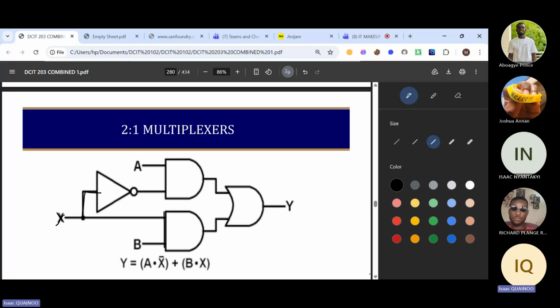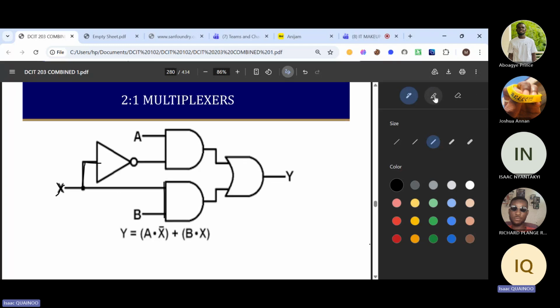We are going to use the same method for other types of multiplexers like 4:1, etc. Okay, so 4:1, we stated yesterday that it has two select lines, right? So S0 and then S1, right? And then the corresponding D output. So if your S0 is 0, your S1 is also 0, then data line 0 is going to be selected. So we said D0 will be selected.